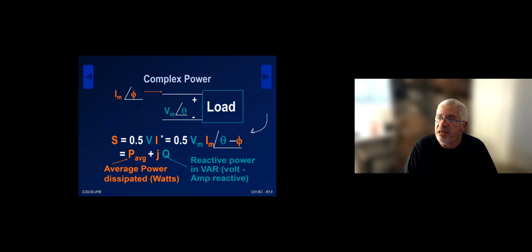What it is essentially, it's a measure of how much average energy is in those inductor and capacitor that make up that load. So by looking at the sign of Q, we can determine whether we're dealing with an inductive load or a capacitive load. Now I'll do a little summary before we end here in terms of what you need to know from a sinusoidal power point of view.